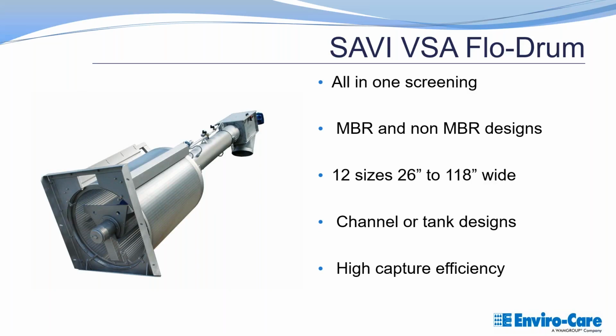They can be installed in a channel or they can be installed in a tank. They have a very high capture efficiency because of the perf blade design and the design of the drum screen itself and the cleaning mechanisms. Makes them very popular for MBR designs as well as regular headworks applications.